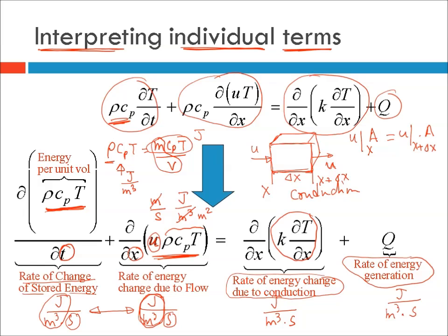Because things are not being compressed, the density also stays the same. So the same mass that goes into the control volume should be the same that's coming out. Because the areas are constant and we are saying density is constant, this is for constant density systems. These are not for compressible cases. Then we have u at x is equal to u at x plus delta x.